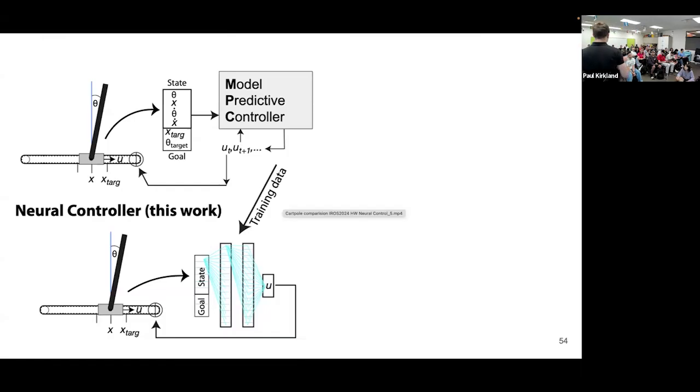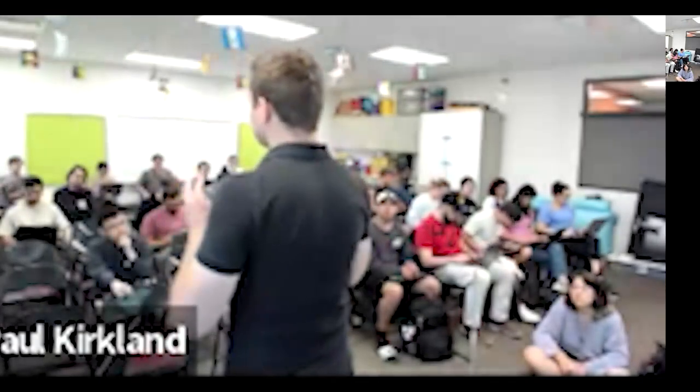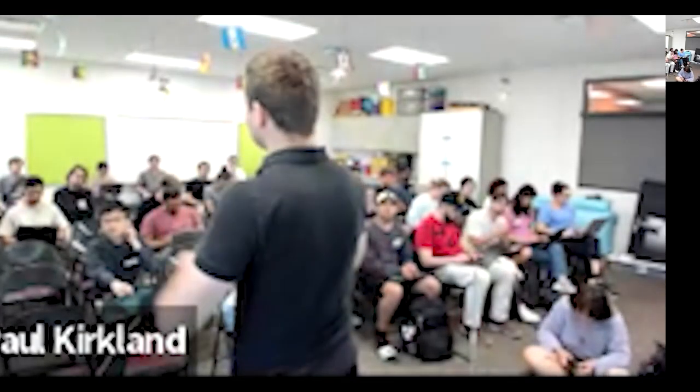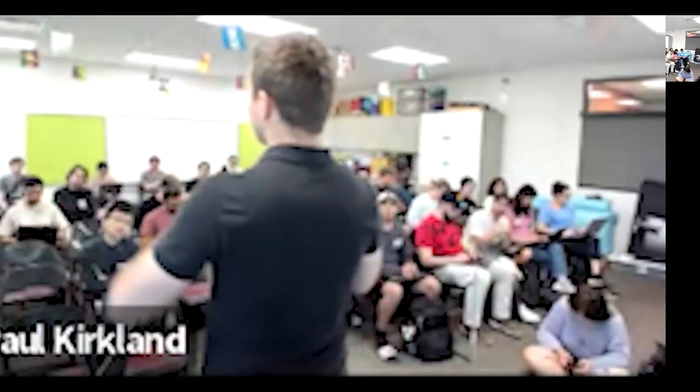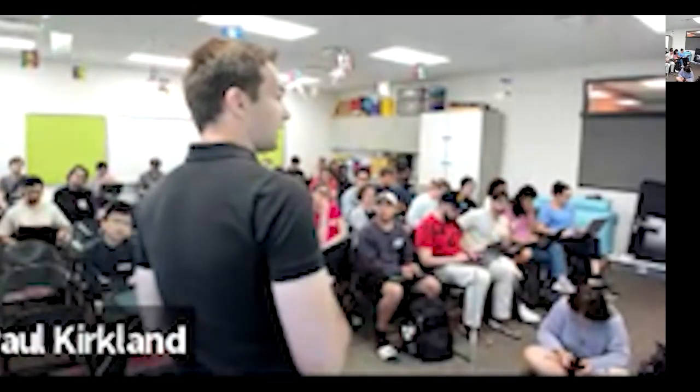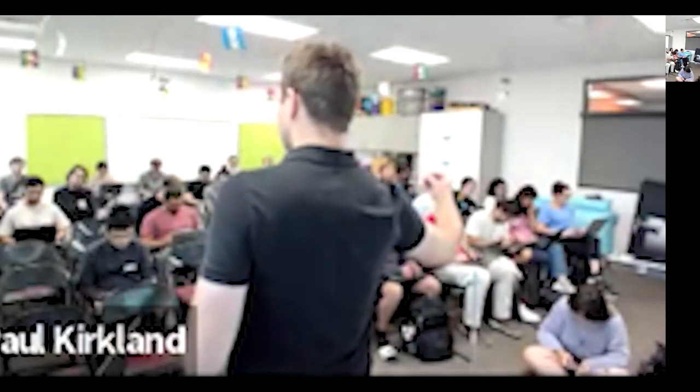Well, imagine that the equations I showed you only allow you to make the step prediction of your robot. If you get a control input, where it will be after, let's say, 10 milliseconds. What MPC is doing is taking this model and solving the optimization problem over, let's say, half a second, and finding the sequence of controls which gets the best trajectory.